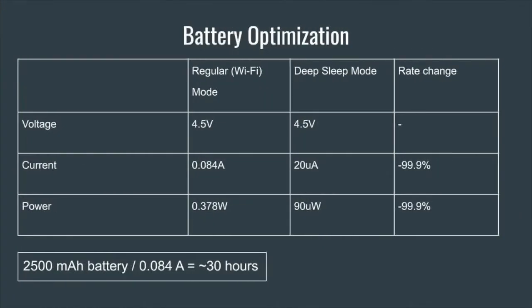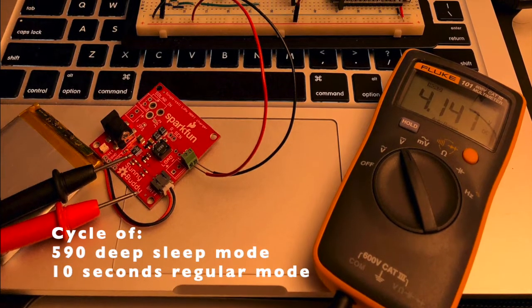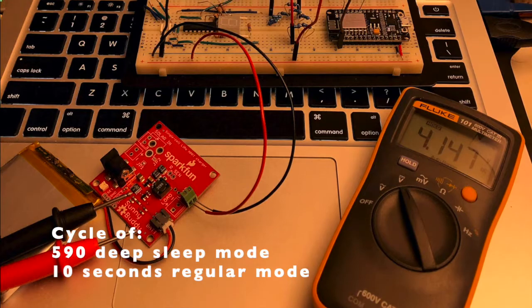With a 2500 mAh battery, the microcontroller can run for around 30 hours. To ensure the device can run in remote locations with long duration, Deep Sleep Mode was implemented to minimize power consumption. As shown on the slides here, Deep Sleep Mode will drop the power consumption by 99.9%. The team has chosen a cycle of 590 seconds Deep Sleep Mode interval, followed by 10 seconds regular mode.